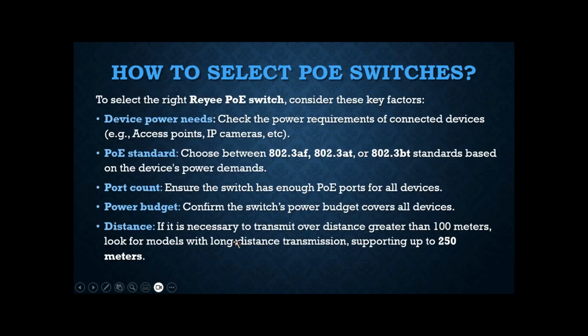So, how can we select the PoE switches? Well, to select the right Reyee PoE switch, we have to consider these key factors. First, the device power need. It is necessary to check the power requirements of connected devices, such as access points and IP cameras. The PoE standard: choose between the different PoE standards, AF, AT, or BT, based on the device power demands.